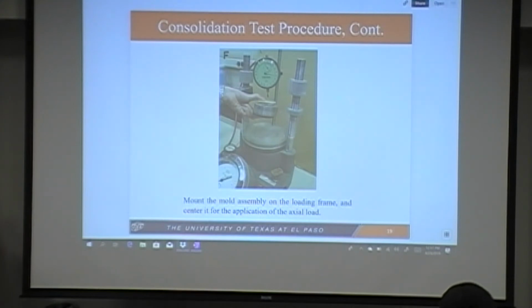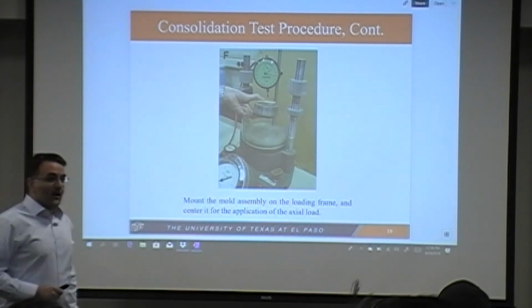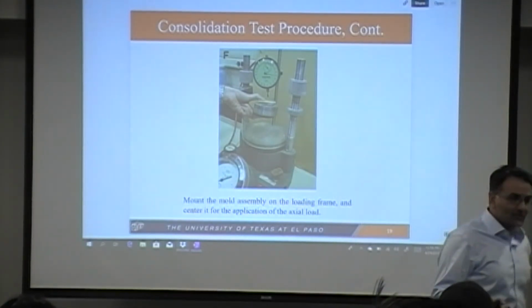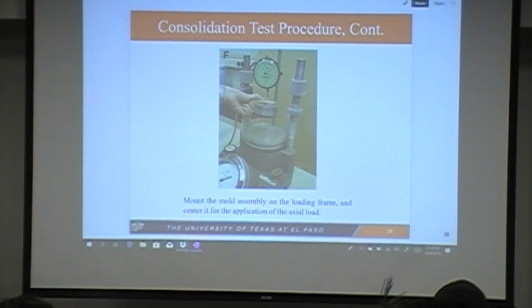Dr. Stern, do you use the same sample through the whole test? Yes, exactly. Yes, it has to be the same sample. Wouldn't adding the weight disturb the sample? It does. It does, and it changes the permeability. And in reality, in the field, it does too, right? When you place a structure at the top of the soil, that also changes the permeability and the internal structure of the soil. So you want to replicate what's in the field. Exactly. That's actually a very good question.